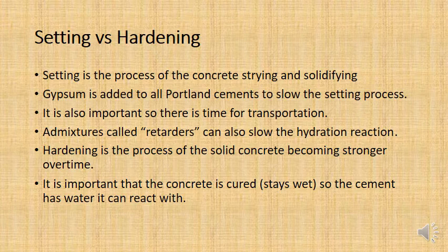And so it's very important that you keep the concrete wet. Even after it's become solid, you need to keep it in contact with water so that the cement has water it can react with, because after it's dried, excess water will want to evaporate out of the concrete. And you want to keep water there to react with the cement. This is a process called curing, and it's about keeping the concrete hydrated. And we'll show more about that in the next lecture.